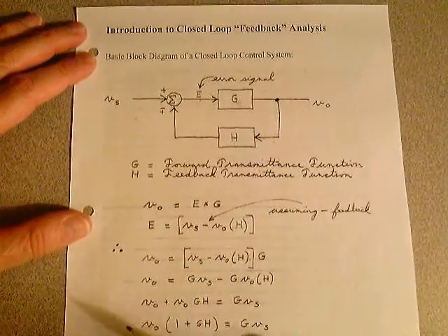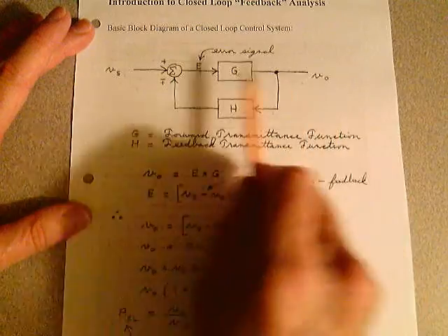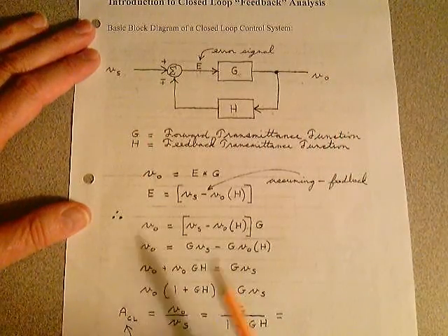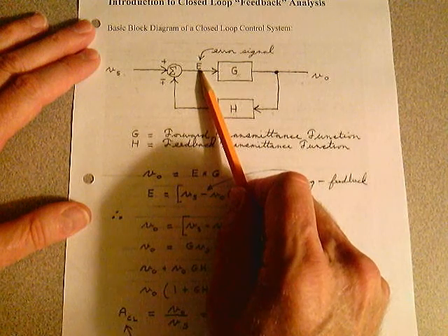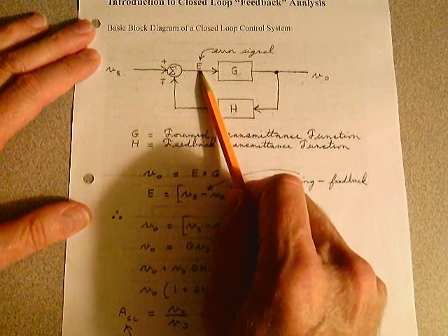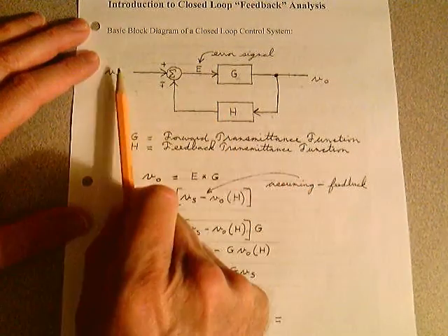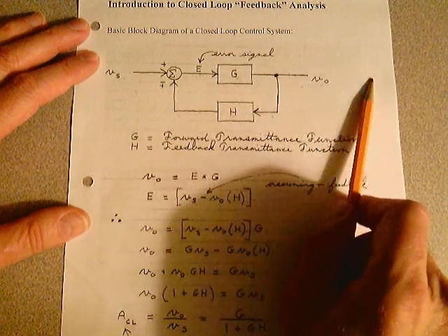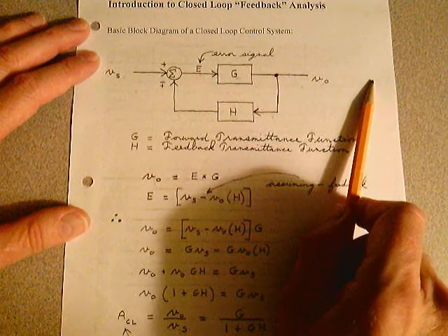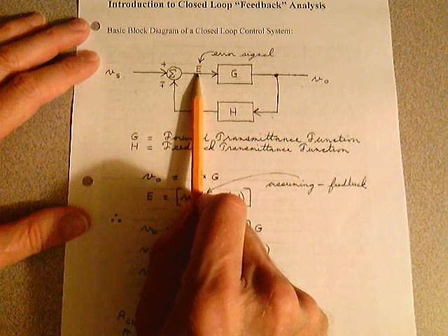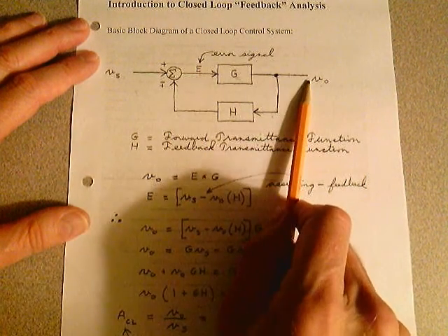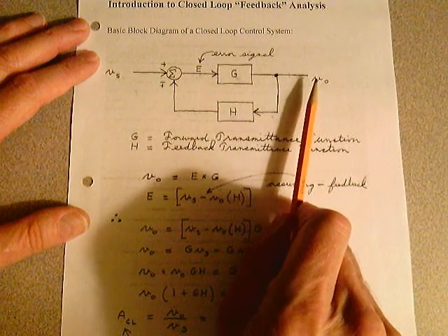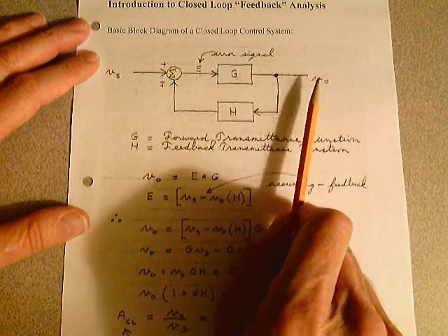What we need to do is work toward getting the ratio of V out over Vs. The way we do that is we define something called an error signal, E. The purpose of that error signal is to take what's coming from the sensor and a little bit of what the output's trying to do to control the device and make correction, so it keeps this stable or controlled.